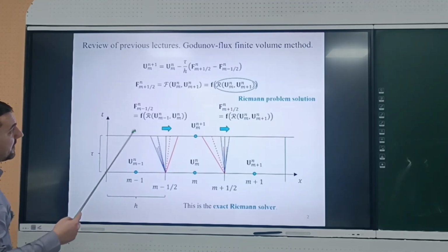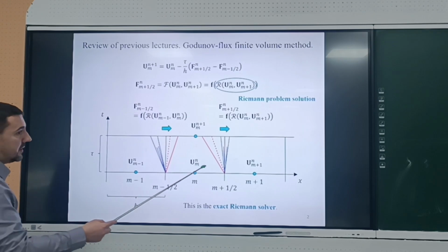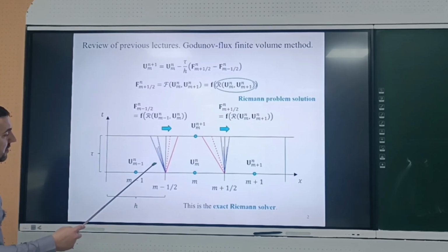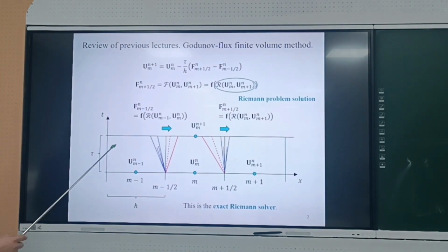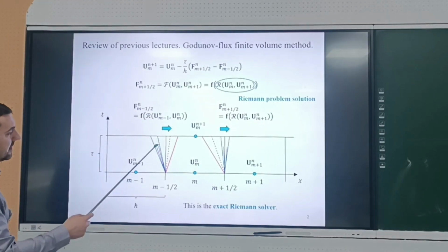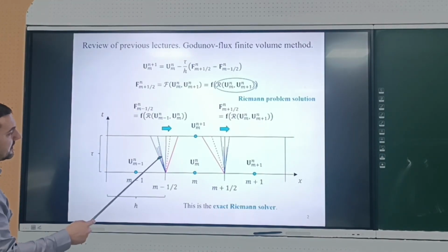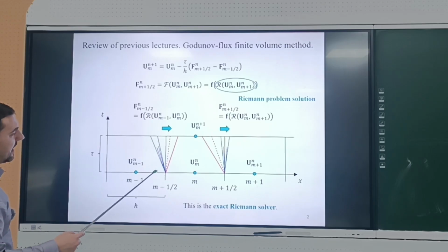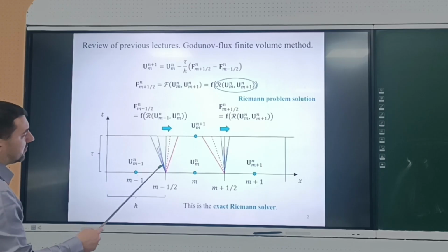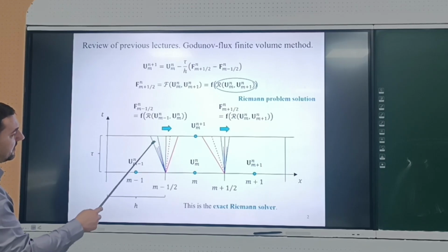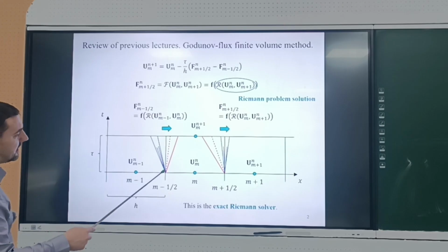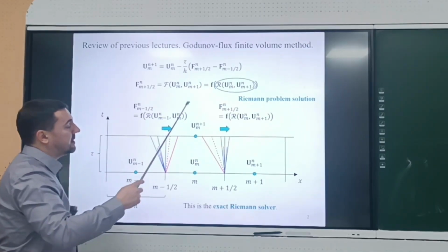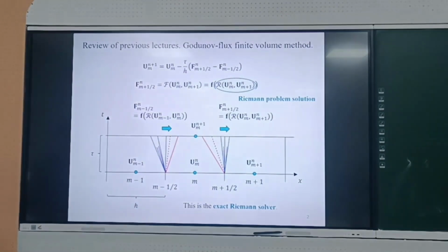And in the Godunov method, we solve the Riemann problem. We get all these structures, and it's important for today's lecture. So I'd like to remind you that we solve this Riemann problem and get these wave structures, shock waves or rarefaction waves, contact discontinuity, and we check. We need to find the region in which the surface between these cells falls in. And then we take these parameters and put them into the flux. And that's the idea of the Godunov method.